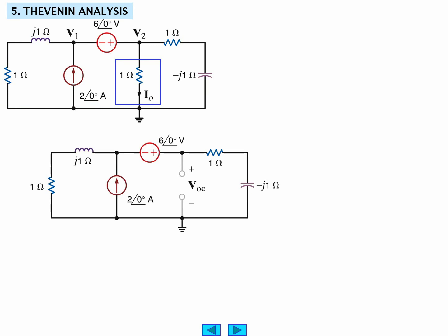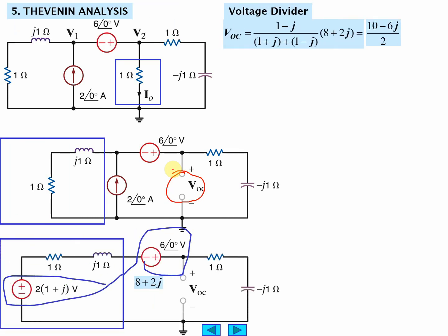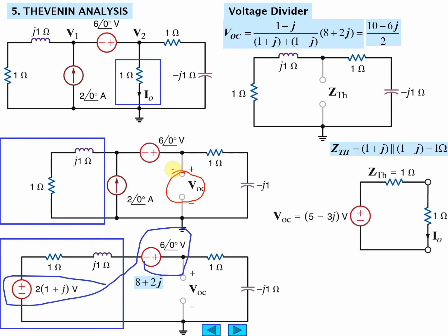This is the load current. You just take it out and you figure out Thevenin's equivalent circuit for everything else. Is this a lot easier? It looks like they've done a source substitution too, changing this into this.